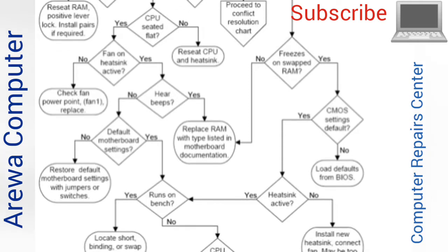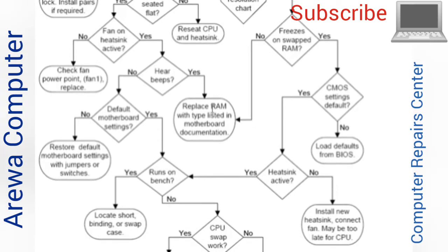As we go through motherboard diagnostics, if you're comfortable with what you're doing, and you're having these strange ghosty problems, really the main test is to take the motherboard out of the case and just run it on the bench with the power supply and with the video card. I don't advise you do it unless you're very comfortable working around electricity, because you could burn the house down, for example, or you could give yourself a nasty zap.